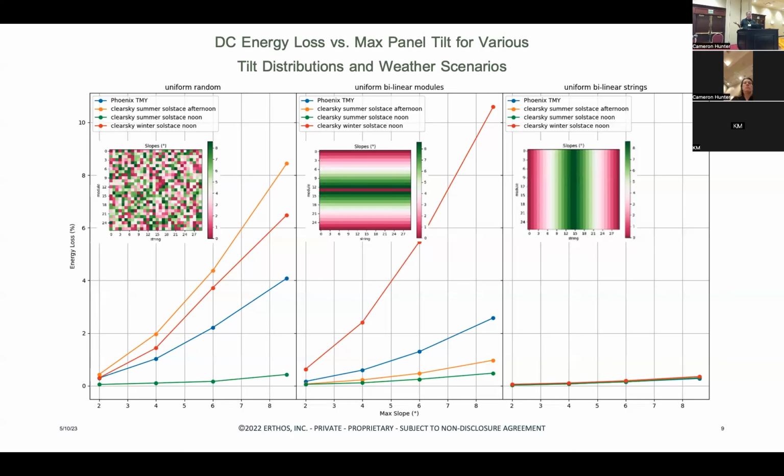And for O&M purposes, when we're modeling, if we have the topo, if we do a LiDAR of the entire array, the entire system, we can use that with PVLib to actually model this, incorporate it, and get more accurate results. And that is all I had.